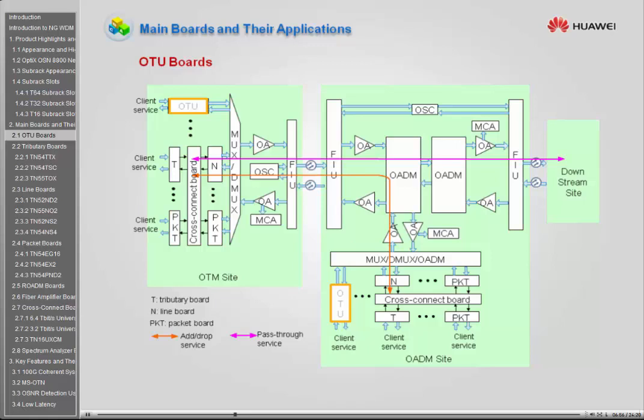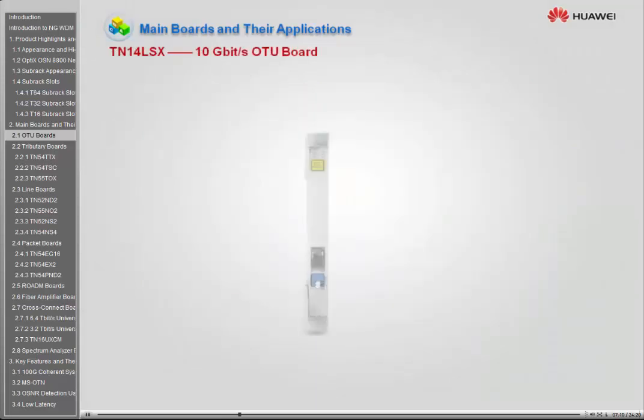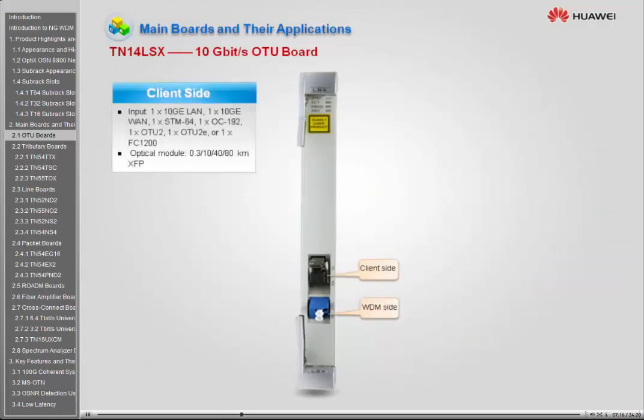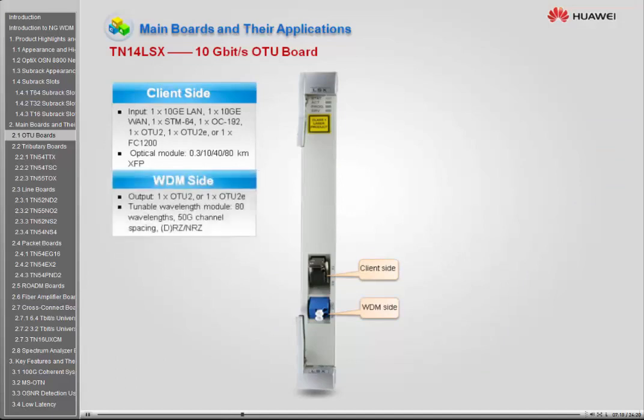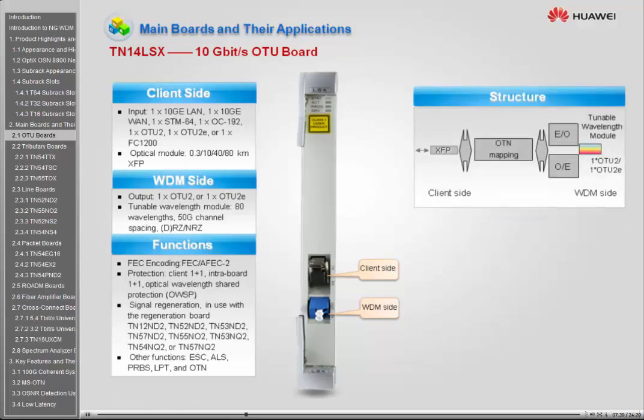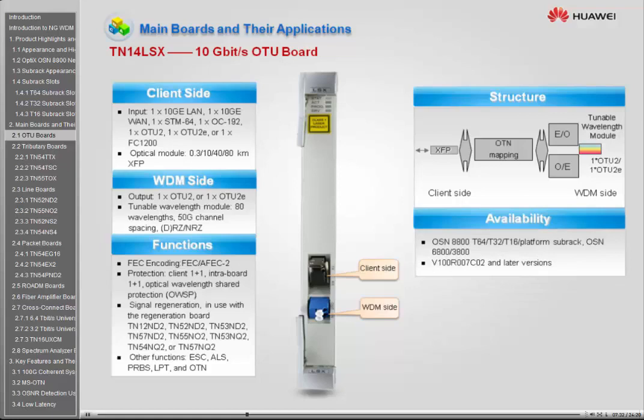The TN14LSX board is a newly added OTU board in V100R007C02. As you have observed, the TN14LSX board is a 10G OTU board. This board supports SDH, OTN, and various Ethernet services on the client side and produces one OTU2 or OTU2E signal on the WDM side.